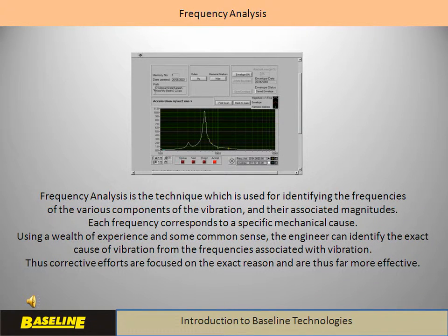In most cases, the technique of frequency analysis of vibration, also known as spectrum analysis, is essential to get to the root cause of the vibration. This technique is based on the fundamental concept that if there is a vibration at a certain frequency, its cause must also be at the same frequency. Thus, frequency information of the vibration is essential to fault finding.